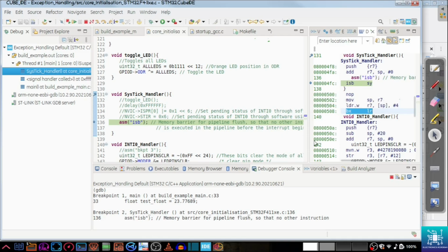So previously we saw a pop instruction. Here we see BXLR, which is the conventional assembly instruction to return from this, and this has been done because the LR has not been stomped over. The LR is retained, so that the BXLR can be done this way rather than doing a pop of 2 values that we saw previously.